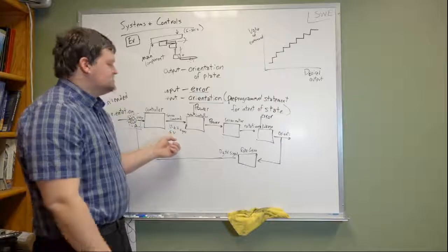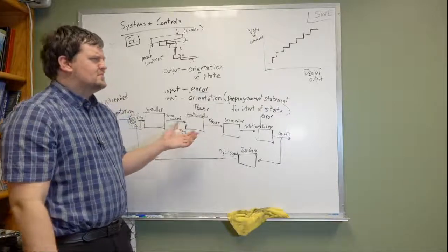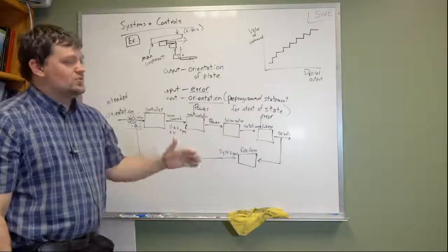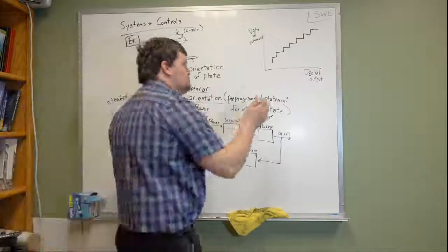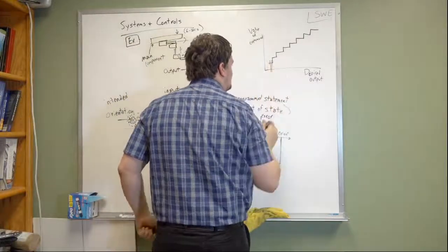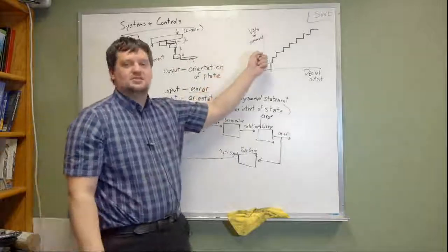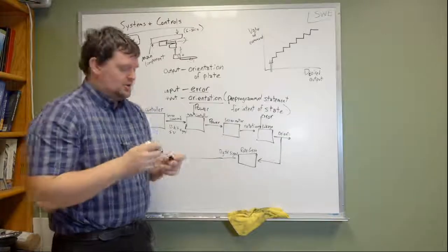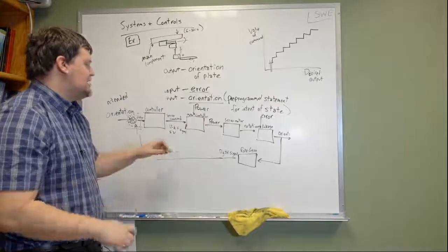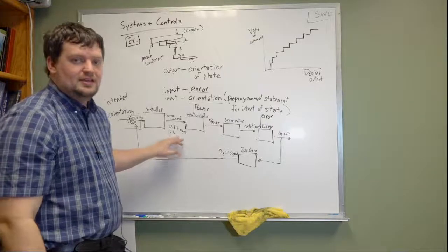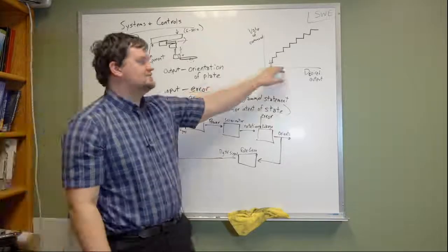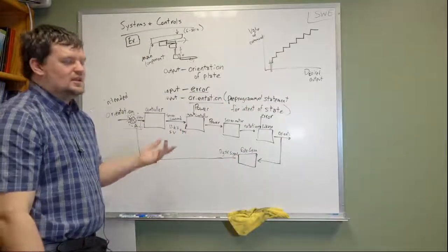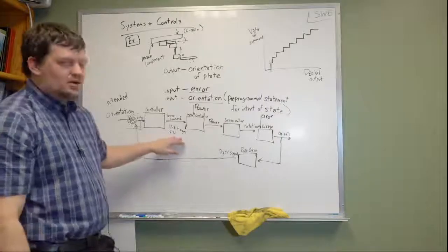We could change this to a 16-bit signal. A 16-bit signal would be something like 64,000 steps. It does make the steps a lot smaller, but there's only 64,000. If we want to have a slight change between this value and this value, the problem is that the command that's sent to the servo motor is going to be the same. Okay, so it's a resolution error, but that error still exists in that now you can't have anything less than the 4096 stepped resolution. You can't have anything better than that. So there's an element of error that's associated there.